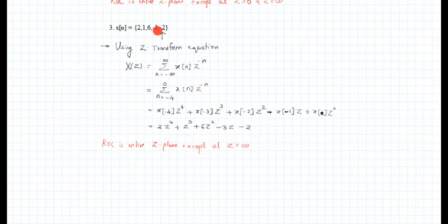So this way, friends, we can easily correlate the input with the Z transform that we obtained. Or if I now know my Z transform, I can make a clear prediction of how my input sequence would be. If my Z transform has only positive powers of Z, I can make a quick analysis that my input sequence is entirely a left-handed sequence.